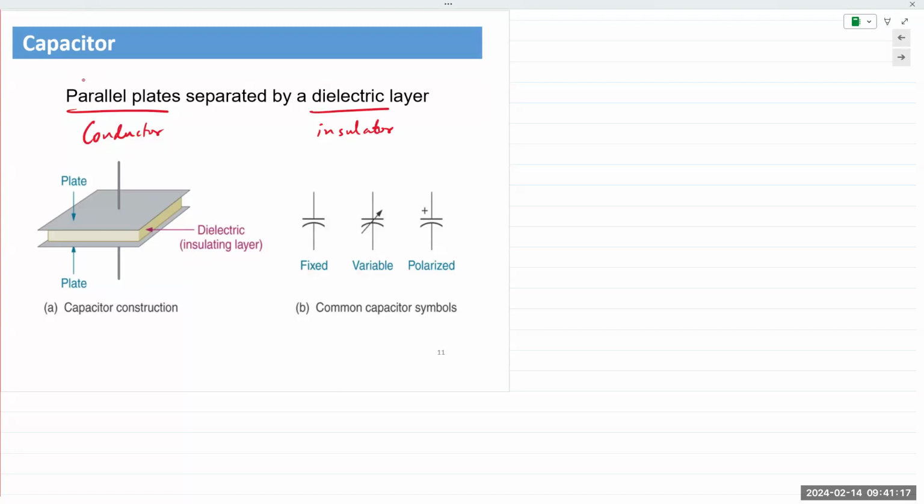And remember what I said about a wire: a wire inherently has resistance, capacitance, and inductance, but it does not rise to the level of interference. You could take the two palms of your hands together, separated by air, and measure the capacitance between them. It's going to be very, very small, but if you had a meter capable of measuring it, you could. So again, capacitance is nothing but two conducting parallel plates separated by a dielectric, or an insulating material.